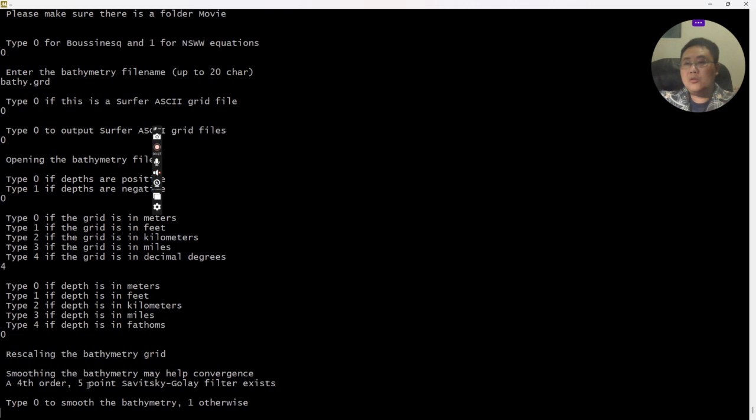Geowave is set up to run two separate subroutines. One is called topics, and this topics is the subroutine that's going to generate the initial conditions. And then those initial conditions are going to be fed into another subroutine called funwave, right? This funwave is a much earlier version, a sequential version of the funwave-tvd, using a different kind of numerical algorithm. So the earlier sequential funwave numerical methods also have some tolerance about the smoothness of the bathymetry, right? If the bathymetry is too rough, that sequential funwave subroutine is going to have instability problems. So here it's asking you to smooth.